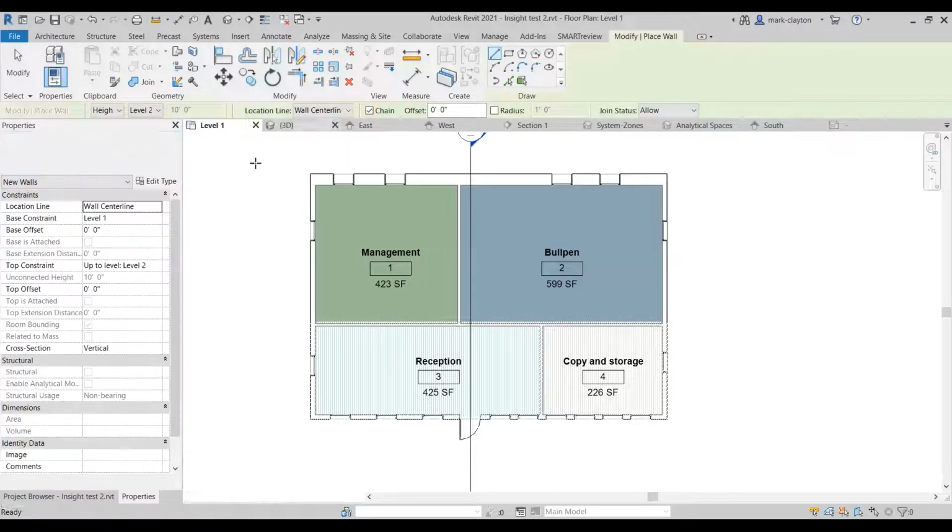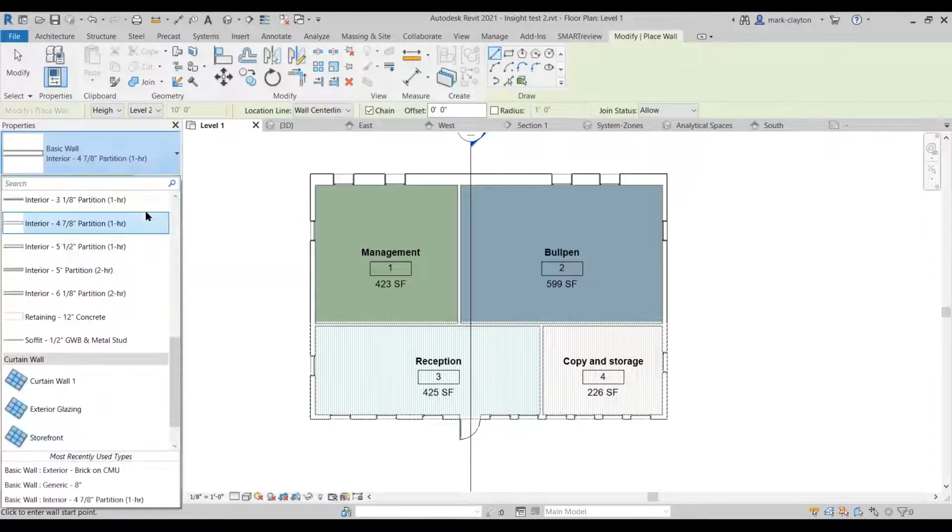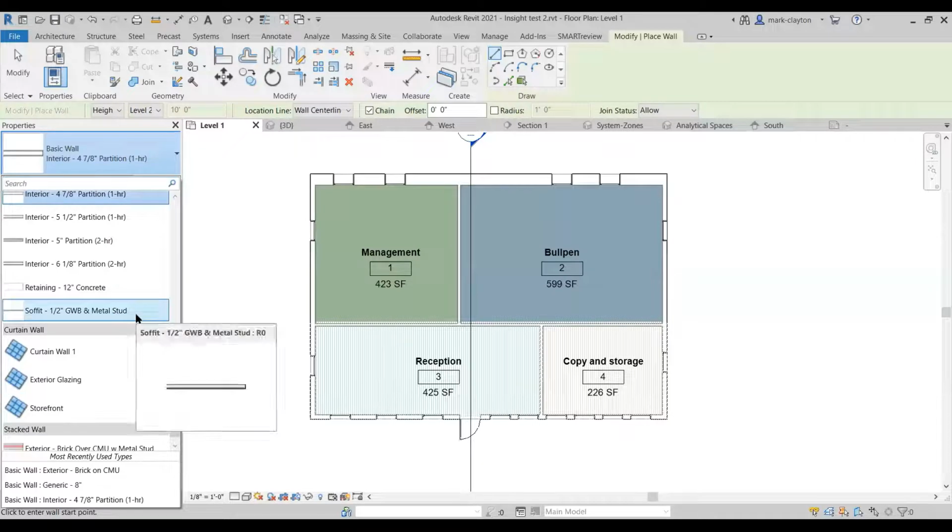But defining what the wall assemblies are in concept is a stronger way to do it, because the concept is more stable than the actual creation of the wall. So I often use these generic ones, which are pretty good.